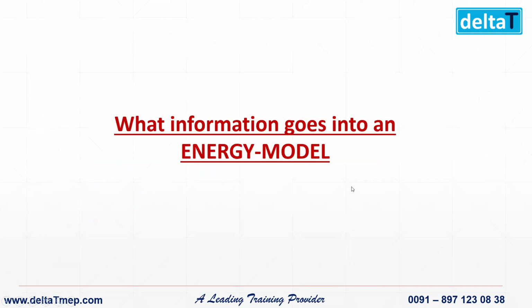So anyhow, what we have learned so far is what an energy efficient building is, and then what energy modeling is. It means we get outcomes: kilowatt hour per square meter for one year, CO2 emission yearly, and how much we are getting as monthly bill. And what standards we are using in energy efficient building, that we have learned so far. Right now, what information goes into the energy model?